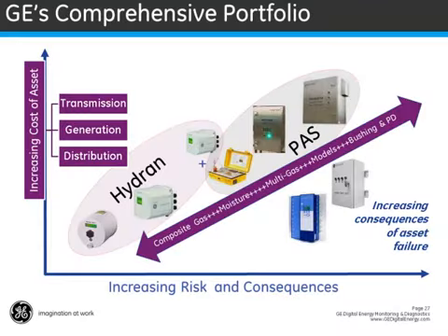When it comes to choosing the correct monitoring system, it can be difficult. However, there are some key factors that one can consider and that can help in the process of selecting the appropriate online monitoring systems for the application. For starters, having a basic understanding of the transformer behavior is critical. Going through historical offline data, looking back at DGA results, bushing results, and so on, can give you a good perspective on what may need to be monitored over what you think should be monitored.